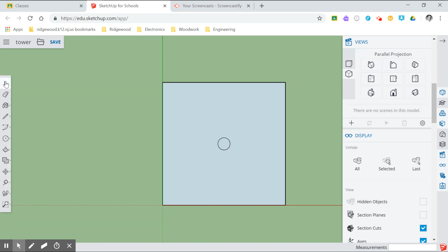So now I have everything drawn that I want, because one thing you need to understand is that whenever you're working in a CAD program, you want to draw everything in 2 dimensions and then change it to 3 dimensions by extruding it out to a 3rd dimension. So I've created the sketch that I want to make my changes to. The only thing I haven't done here is created the hole. So I've made a drawing of the circle, but I haven't created the hole.